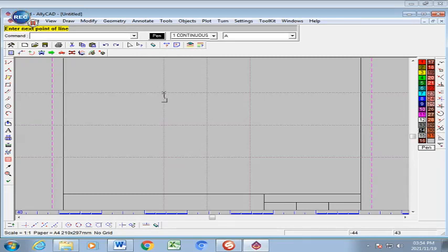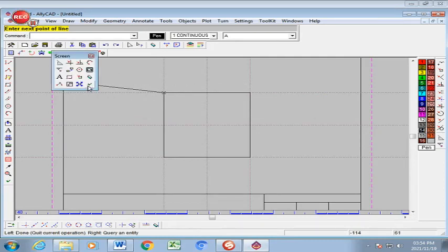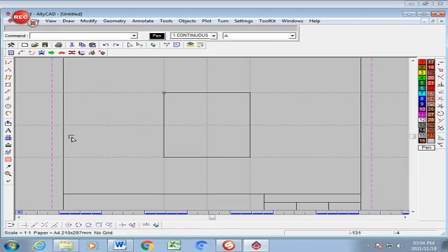So I'm going to click on the box just once, and I have this line now that I can move. So I'm going to click in at my next point, click at my next point, and click here. Even though I'm not doing a straight line, it jumps. So there I have that. Now you still have the line connected to the cursor, so you have two ways. You can either press the spacebar, or you can left click on that specific thing over there, which is your green tick.